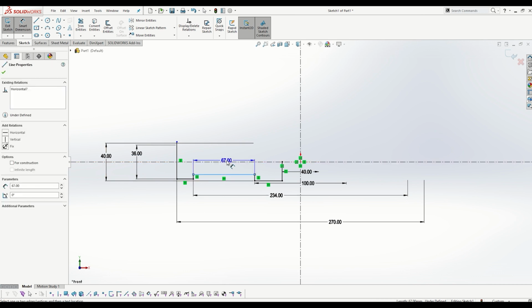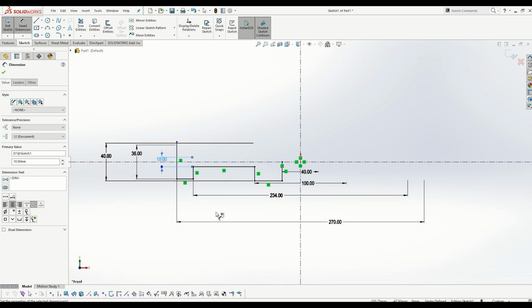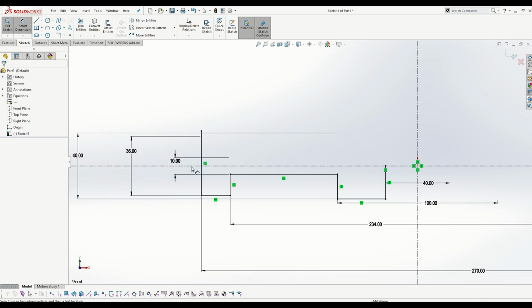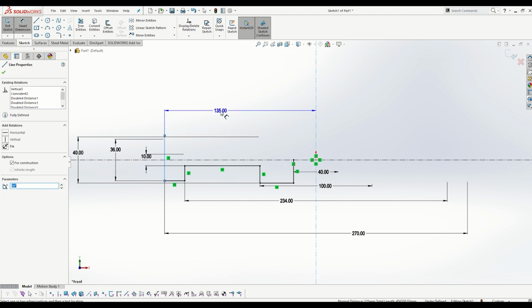So they have the in-between material as 10 mm. One thing you have to check while doing a revolve: while doing a revolve sketch, if you have the diameter, you just use it with the help of a center line. You just convert it to a diameter. Most of the time we are working with the radius only, so that will go wrong. You just check that one.